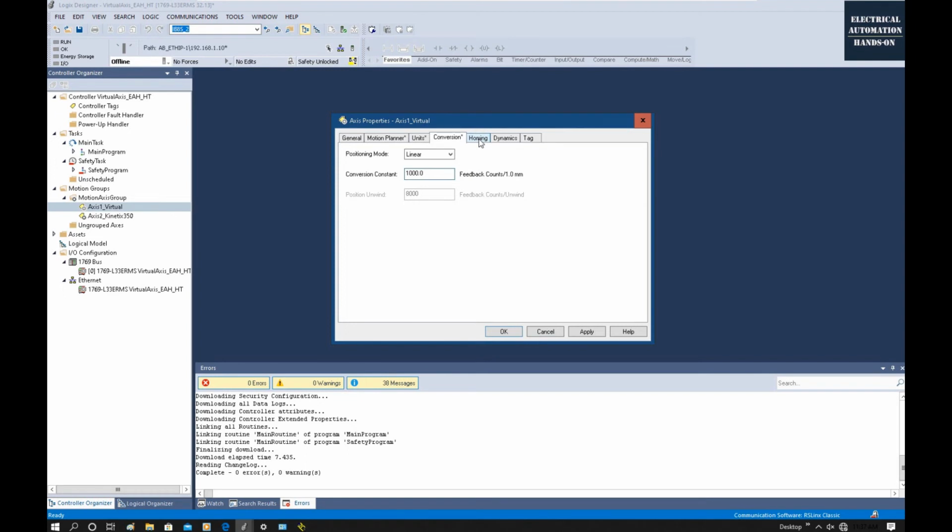And then let's go to the homing. For the new learner, we need to separate the two ideas, home and a 0 position. These are 2 different ideas. Home basically associates with your actual application, for example, the initial position of your access, or basically where your mechanical system stays as a parked position.